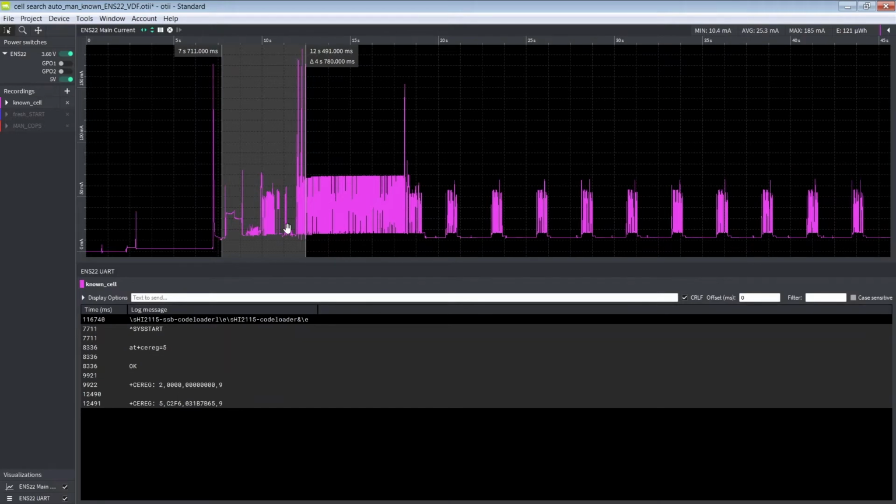So any smart meter, for example, will not move. And as soon as the smart meter has found its cell and wakes up after, for example, a PSM period, it will just try to reattach to the last known cell first and to the last known network. And this is quite fast then, and of course the best solution we can have with an average of 25 milliamp only for 4 seconds. So this is quite fast and usable.